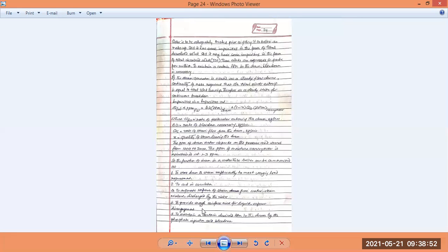To maintain a certain desired ppm in the drum, phosphate injection and blow down is required. Here we are not doing cleaning in any artificial way, but we are using different types of phosphates, which will react with the salts and create a compound with the salts, which will then be blown out. This salt compound cannot get deposited on the surface of the superheater, so you can easily blow it out to clear the whole matter.